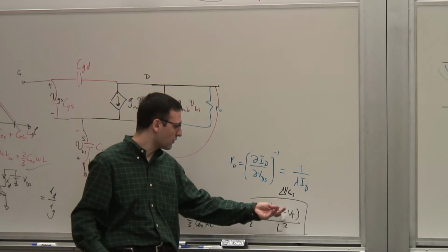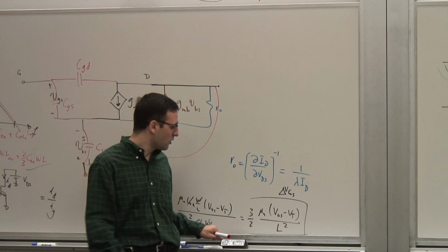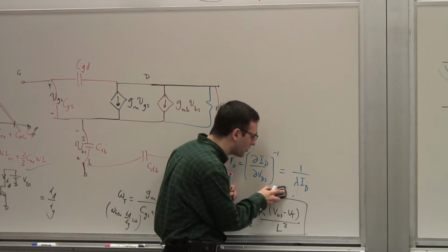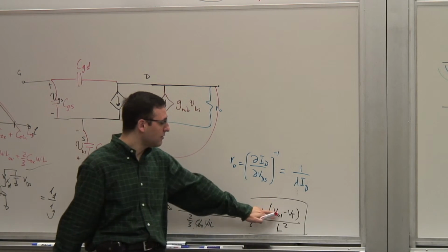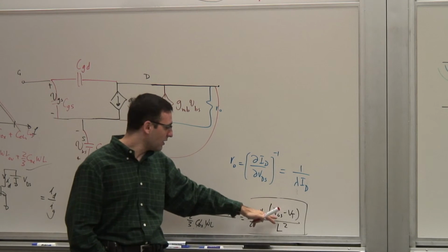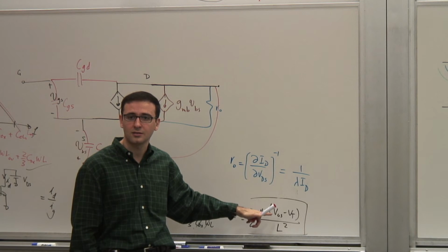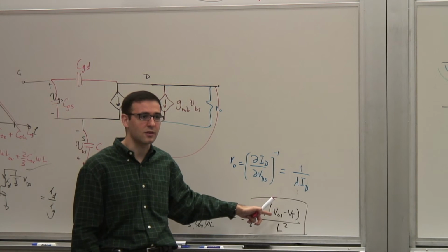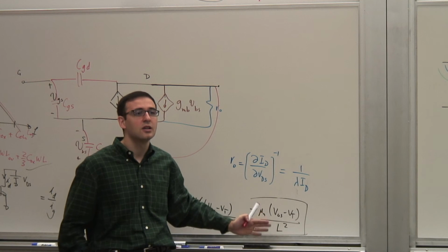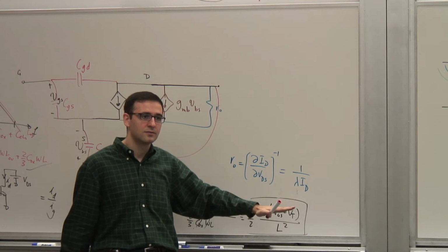How much extra voltage you have in addition to VT, which determines how much inversion charge you have. So it depends on your gate overdrive, and that directly controls your current, right? So it basically tells you that if you want to make the transistor faster, you've got to burn more current. So similar to a bipolar transistor, right? Remember that? If you want to make it faster, you have to burn more current.